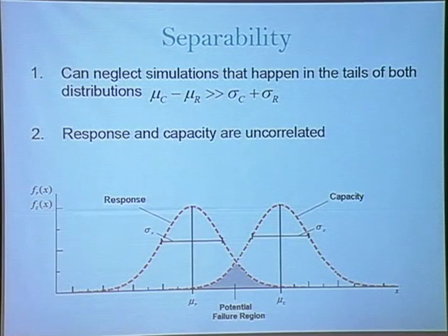So this plot says that if we have a structure with unusually low yield stress and unusually high stress, then we'll probably fail? That's correct. If you have a combination of unusually low yield stress and unusually high stress, it will fail. But what it also tells you is that you don't need both of them to happen together.